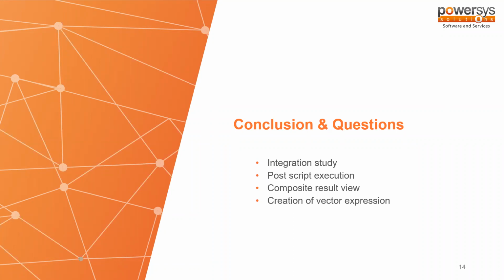Maybe before answering this question, I will mention the fact that right now we don't recommend RT to be the source of the creation of the efficiency map, since we introduced efficiency map studies, I think two or three versions ago. This should be the place where you create efficiency maps. RT is not the tool now to create efficiency maps. It was in the past, but now please use efficiency map studies.